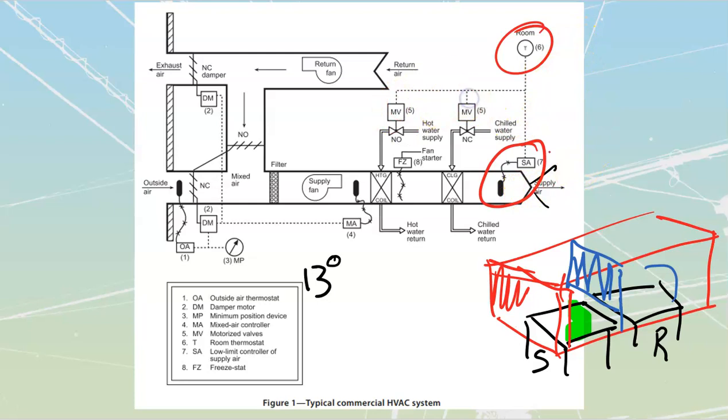It's going to be a comparator system that's going to work inside here. It's all controlled digitally inside of these. Same with if my room temperature senses that it is too hot. Whatever I've got inside of this duct over here is too hot. When it compares it to what we've set the room to be, it is then going to activate this motorized valve to cool, sending cold water through those coils over there.